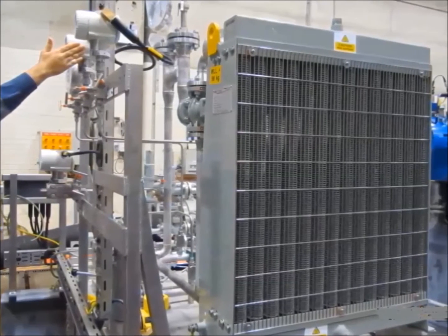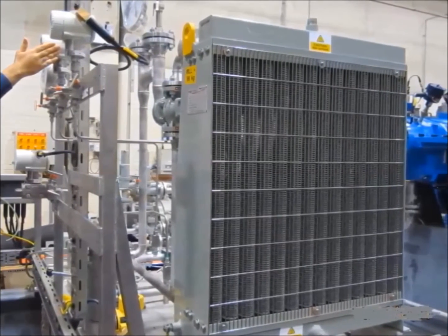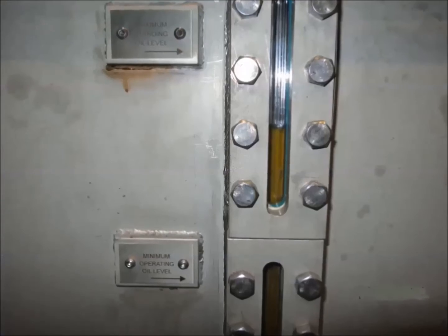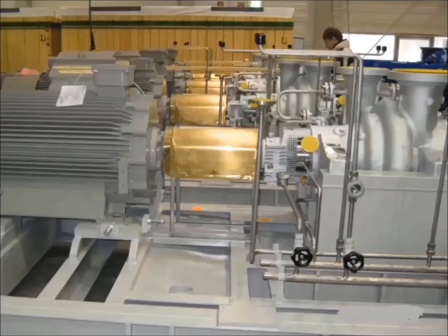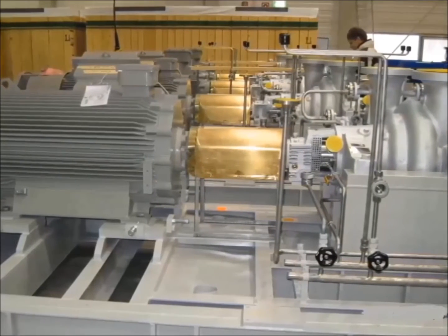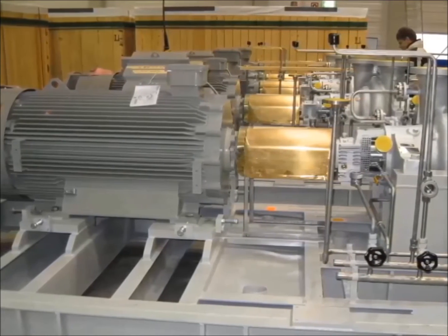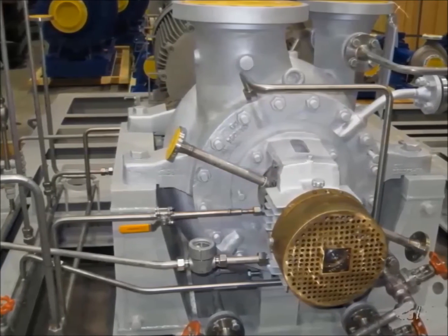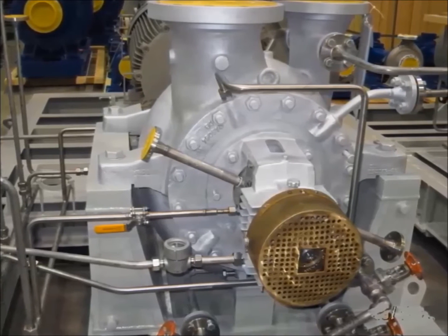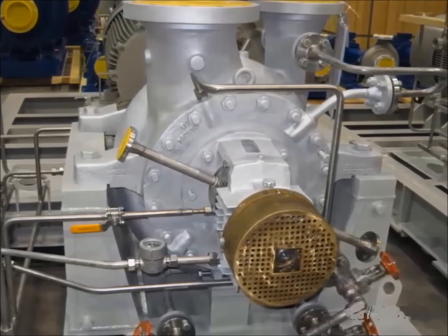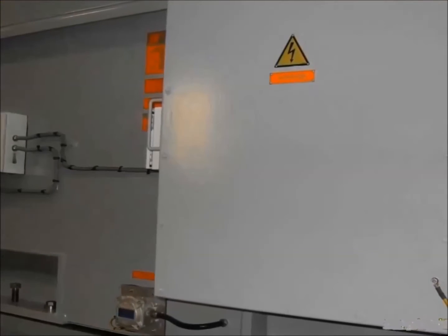The FAT from one equipment type to another is different. For example, the FAT test for gas compressors is very different from a centrifugal pump. The details of the FAT test are extracted from construction codes and are summarized in the inspection and test plan sheet. Some vendors only call performance tests a FAT, but the majority use this terminology for all of the mandated tests that are needed to be done in the manufacturing process.